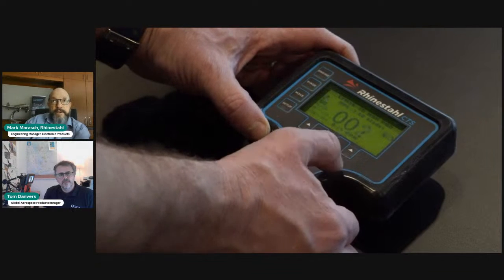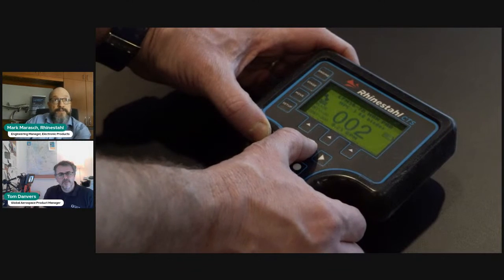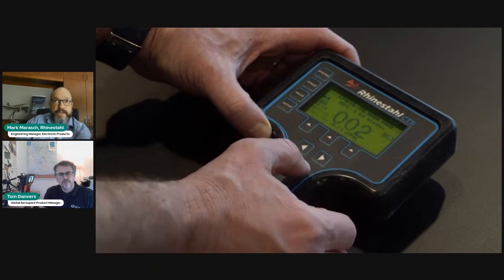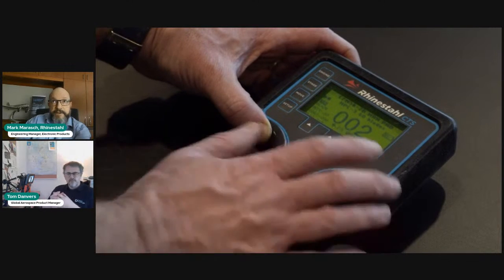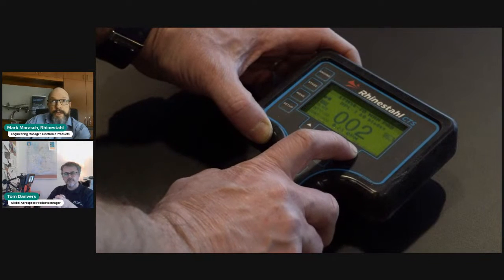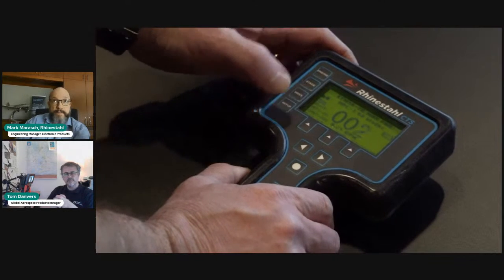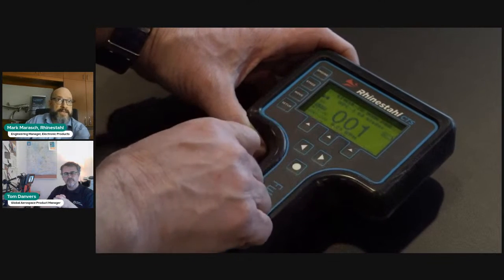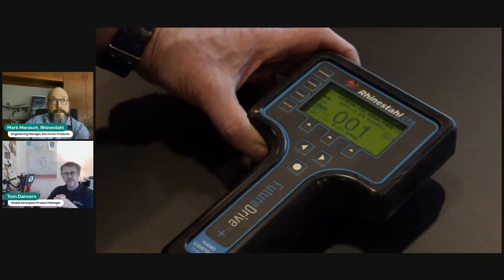Now we're going to jog the engine around until we've placed the first blade, blade 1, into the desired position. Anytime we reverse directions, you'll see the backlash screen pop up. And once you've set it, you hit the set view position button and it records that position. You can either hit the button a second time or you can move into any of the move menu items and it will reset the screen and show you that you're now on blade 1.